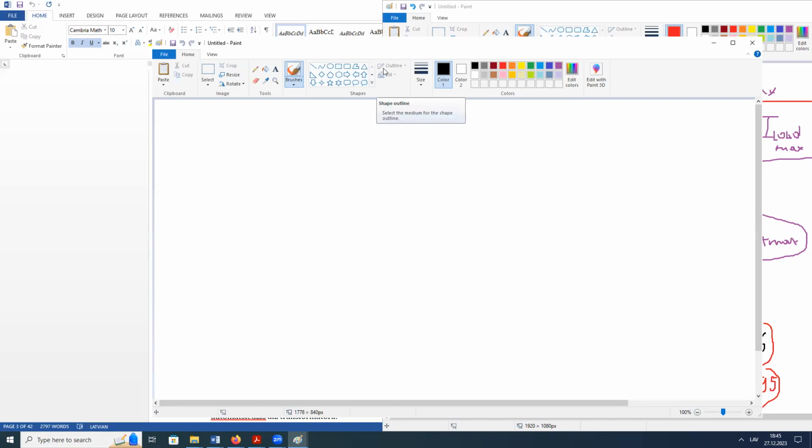First of all, let's discuss the situation. Okay, we have a symmetric three-phase fault. To make calculation easier for us, we use a coefficient like 0.866 to calculate the two-phase fault current value.